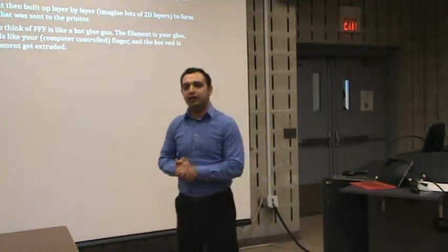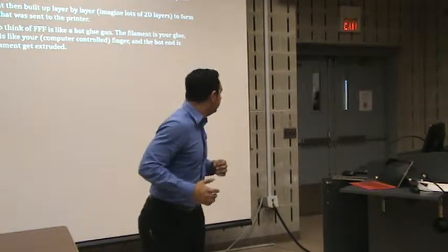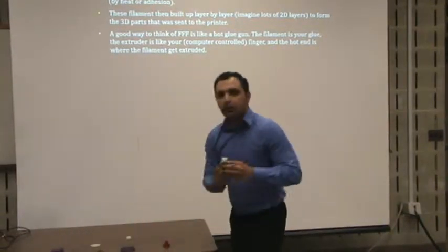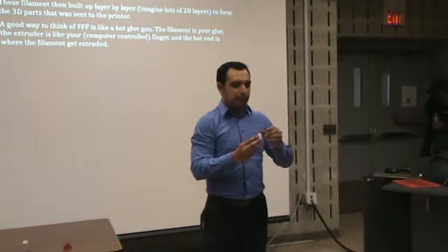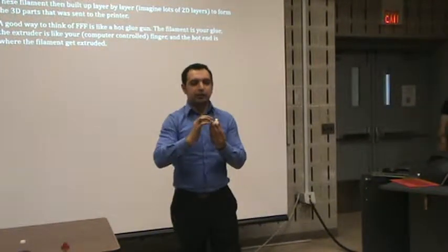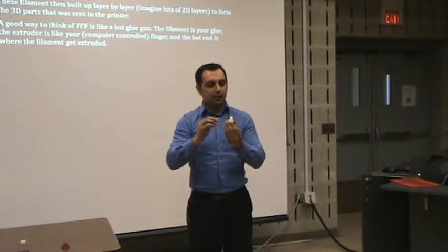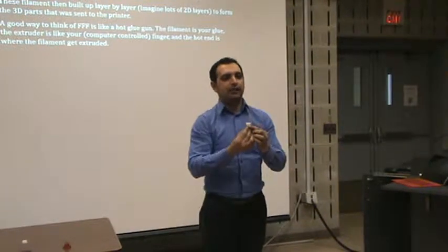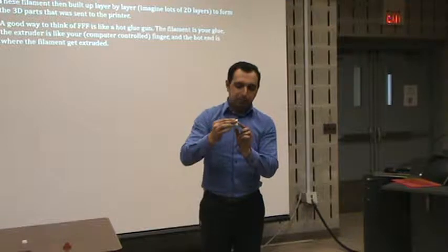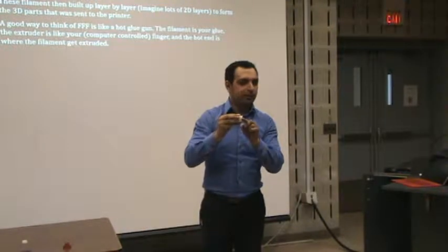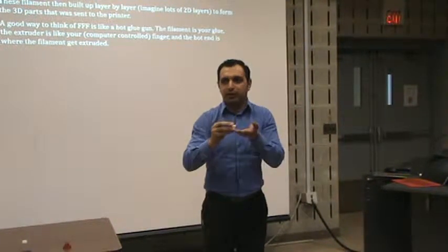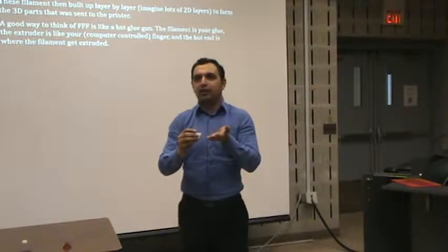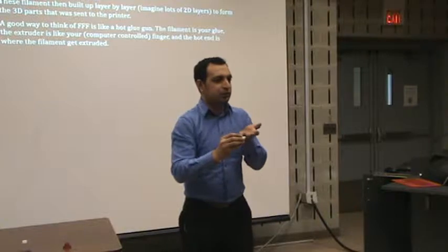And the reason for having a dual extrusion is, well, there is another reason to have a dual extrusion. For example, I'm building this from the ground up, right? So it goes layer by layer like this. Sometimes what happens is, let's say I invert the model and I want to print it like this, right? It will print up till here, but when it tries to print this part, it will just fall off, right? Because there is nothing to support it. Okay, so you have to be careful how you align your model, so that there are no sharp angles.